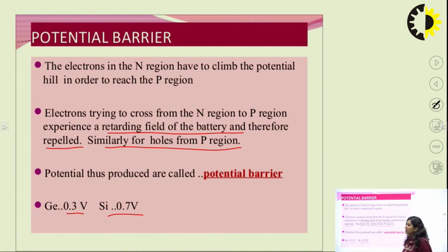What we are seeing here is that the potential barrier keeps on increasing in the case of reverse bias, but in the case of forward bias it keeps on decreasing, and that will help the electrons and holes to move properly across the junction. For this we have to see what the earlier potential barrier is, and if we provide forward biasing, how the potential barrier keeps on decreasing. You can do this in experiments also in the lab. You can draw the characteristic of the PN junction.